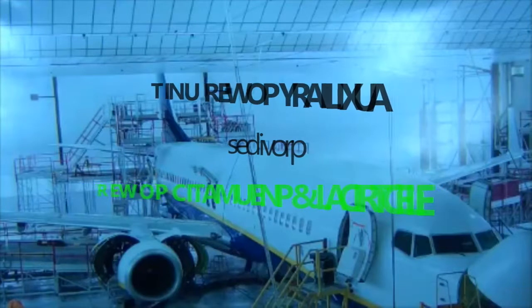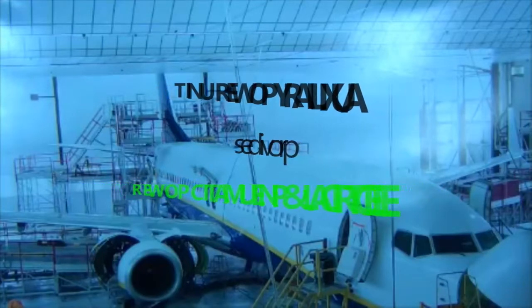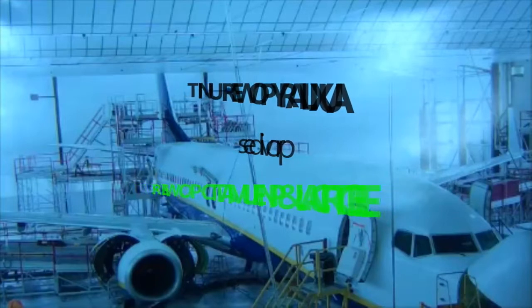And then you've got a power section there. Of course, you've got the exhaust section after that. But you've got to have the air come in, get compressed, and then mix with the fuel mixture. So you have the fuel air mixture in the combustion section, then your turbine section. And after that, you have an exhaust area.